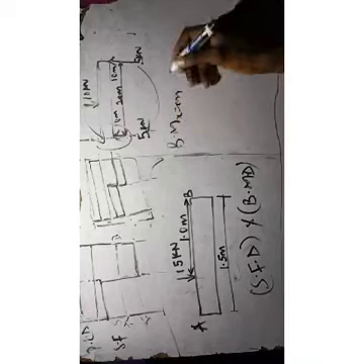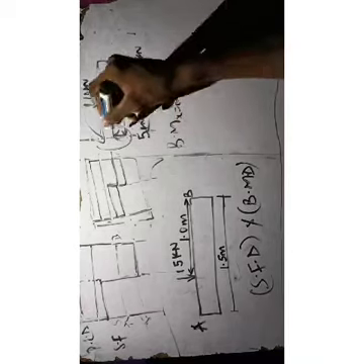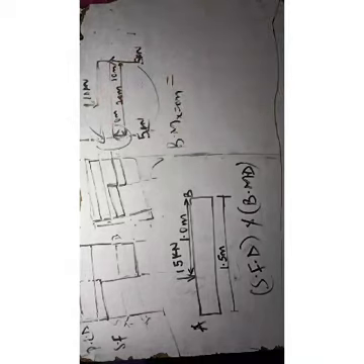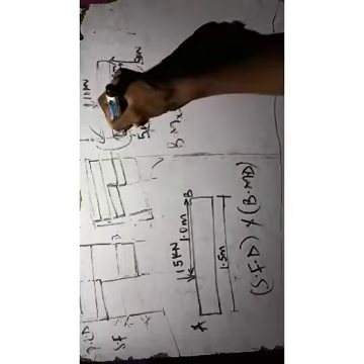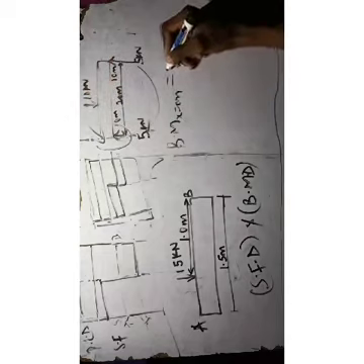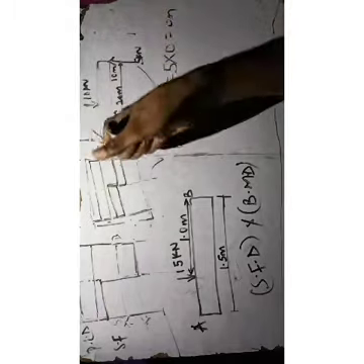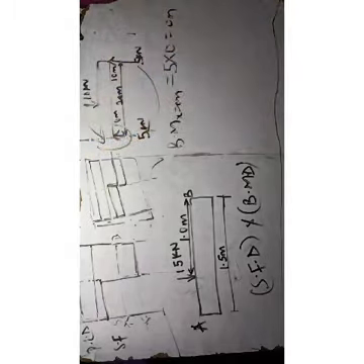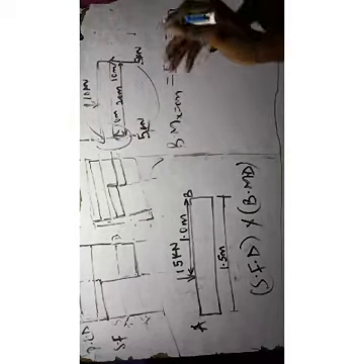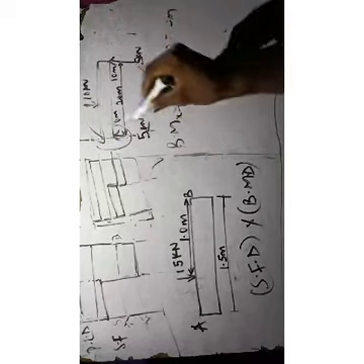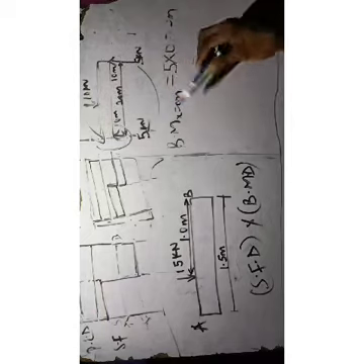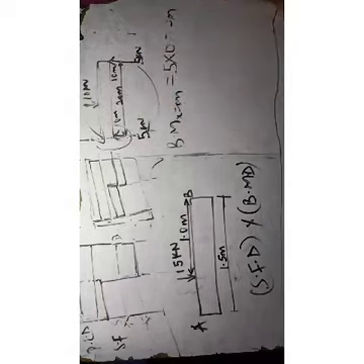when x equals 0 meter will now be equal to 0. At the beginning and the end it will always be 0. Okay, don't forget that, because the bending moment is force times distance. The distance here is 0, right? The force here is 5. 5 times 0 meter is 0. So it's just very useless, because the bending moment at the beginning and the end is always 0.